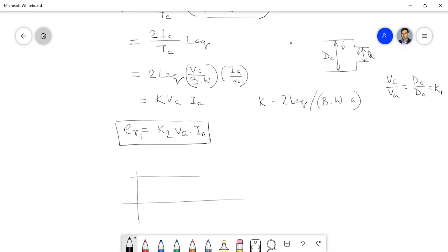If we start our discussion with the linear assumption, the current changes from plus IC to minus IC linearly in this TC time. So this is the linear commutation. But what kind of problem may arise due to this reactance voltage developed in the coil going under commutation?